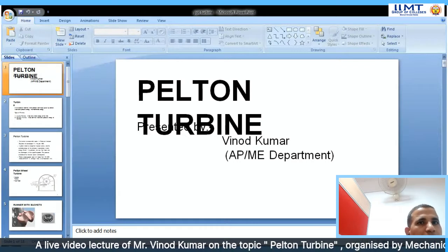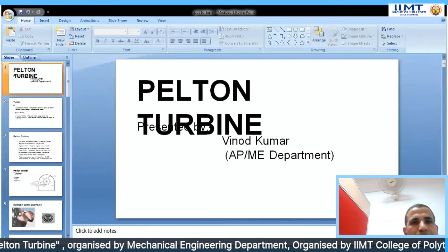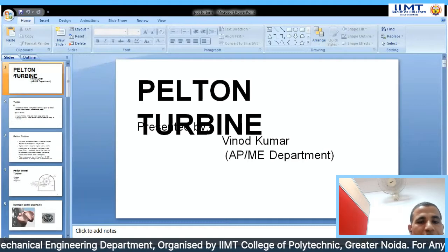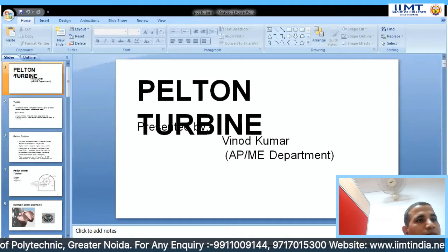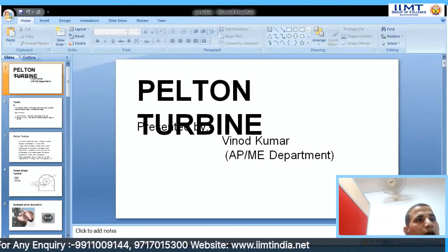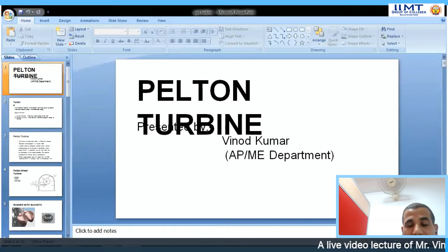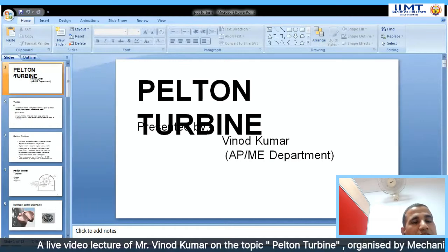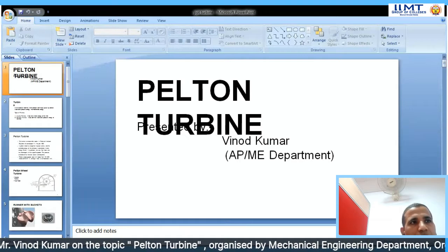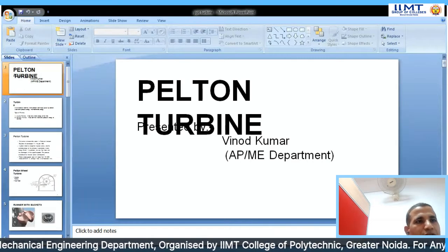Let us see the various components of this Pelton wheel turbine. We have seen the casing here. We have some different diagrams, and now see the penstock. We have already discussed that the penstock is a pipe of large diameter, and the nozzle is attached to the other end of the penstock. The purpose of the nozzle is to convert the pressure energy into kinetic energy.